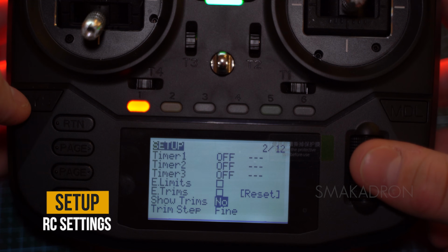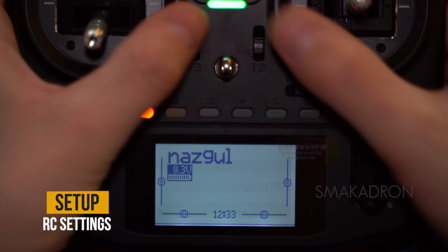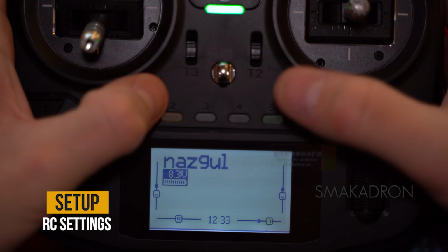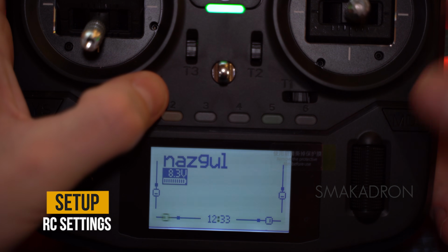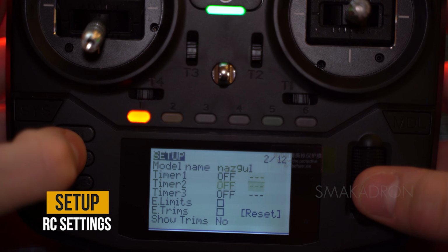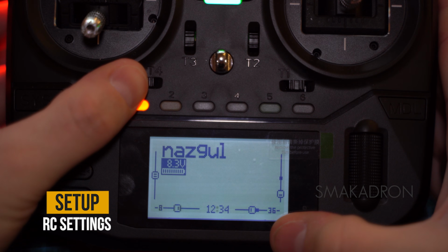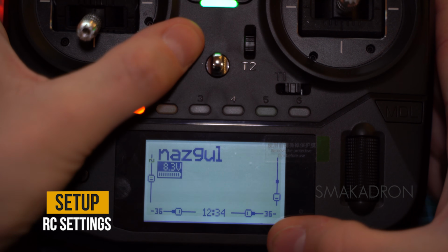Show Trims is responsible for displaying the trim values on the main screen of your radio transmitter. When this option is enabled, you will be able to see the current trim settings for each channel during flight or setup. If disabled, it is not displayed on the main screen. Change displays the numerical value of the trim deviation.